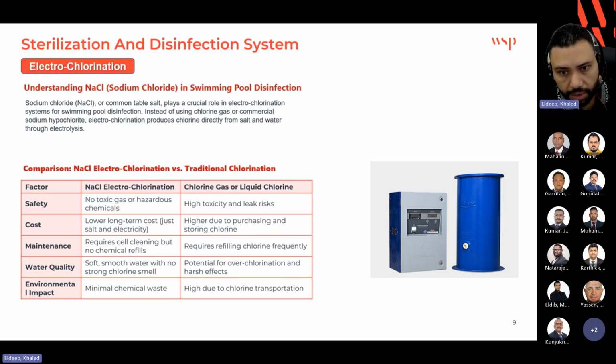In this table, we show a comparison with the other traditional chlorination methods. If we compare it to liquid chlorine, for example, the electrochlorination system provides a more stable and more effective alternative to buying commercial sodium hypochlorite, as I just explained. So instead of continuing to buy material from vendors, I am generating it in my home, I mean on site. If we compare it to the gas one, it is much safer than handling hazardous chlorine gas cylinders on site. So it is much better.